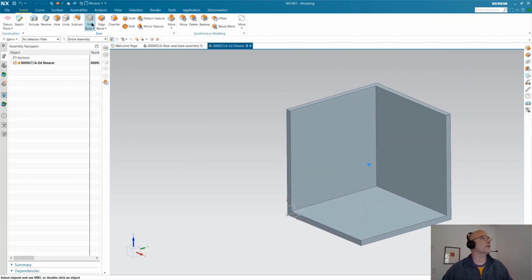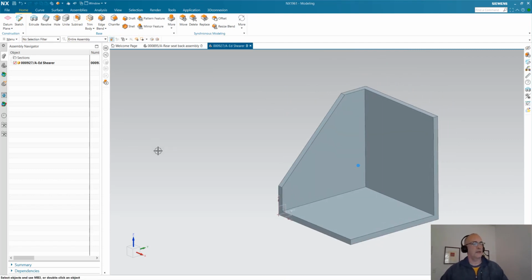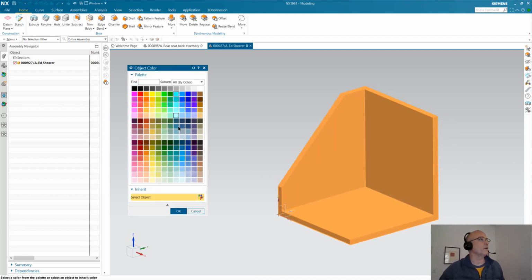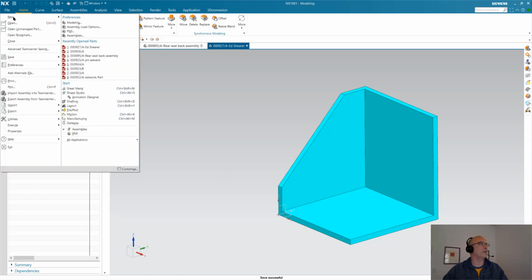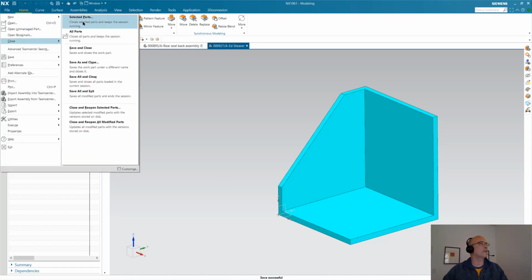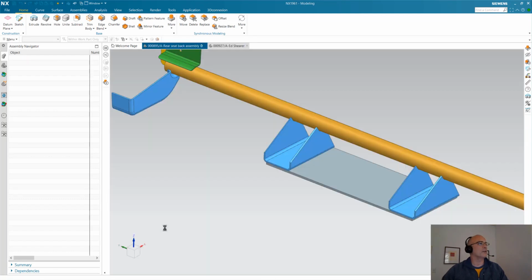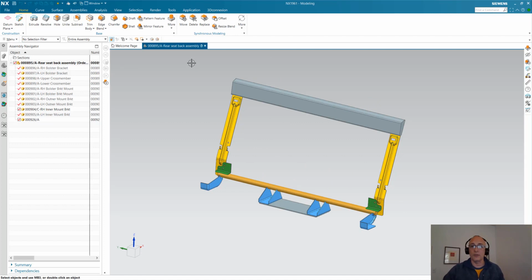And it's falling off the screen, so let's put a chamfer on there. That looks good. And I'll go ahead and change that color. Save my part. I just used a hotkey that I typically use, and now that I'm done with it, I can go ahead and close that. So since I've got 927 there, go ahead and close that guy. Brings me back into my assembly because it was already open in another tab.